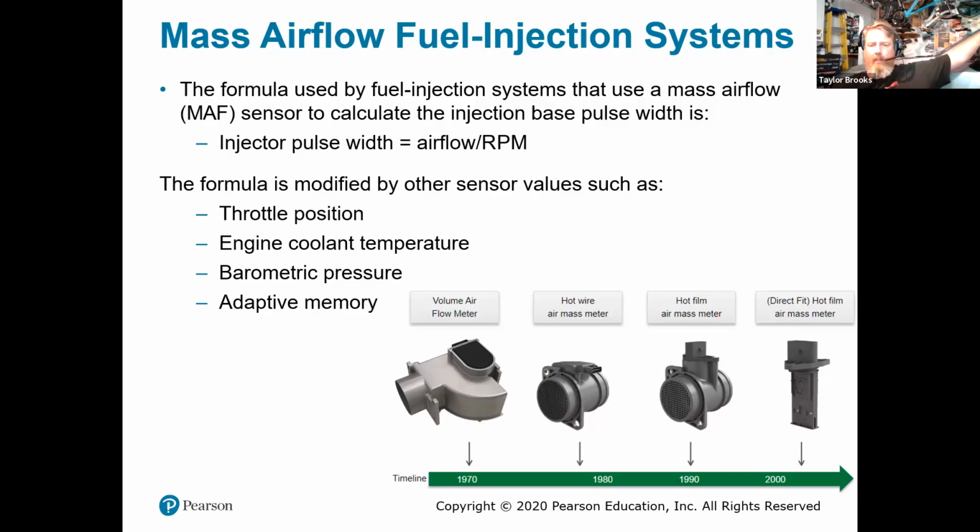But the other style is the hot wire or hot film style. They will be using an ambient temperature sensor so that it can predictively figure out how much the hot wire or hot film is losing temperature, and therefore it can calculate that airflow. Now, the downside of these systems is obviously if there is any junk or contamination of that hot film or hot wire, it won't function correctly. Quite honestly, the trapdoor systems actually work pretty well as long as they're working correctly.